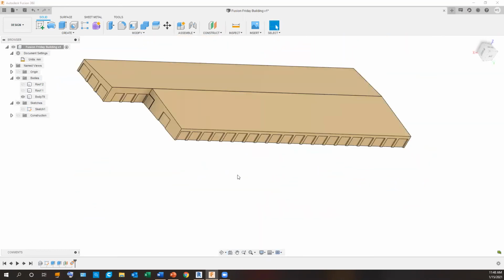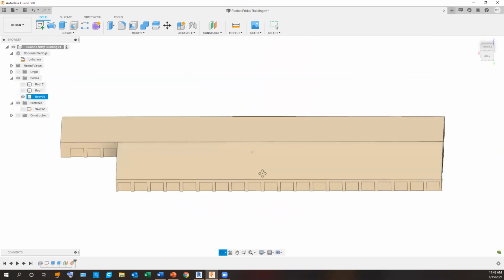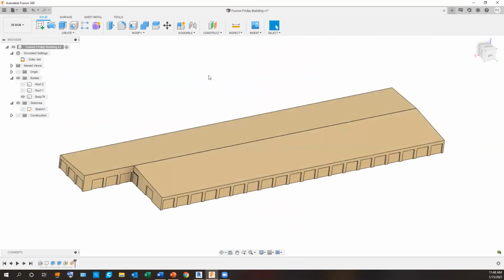Yeah, and you can also control the infill inside of the preprocessor, right, Mark? Like decide what the infill is going to be, shell thickness and whatnot for this specific print. Yeah, when you pull it over in the slicer, if you leave this as a solid model, you can actually tell the slicer how much infill that you want as a percentage. So it's not going to use material and completely fill the inside of the model. It'll do some type of pattern that you select and just fill in a portion of it.